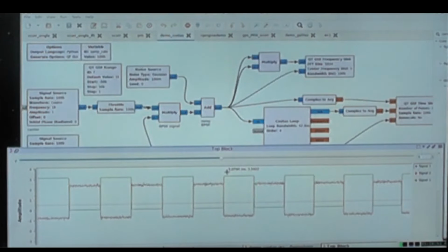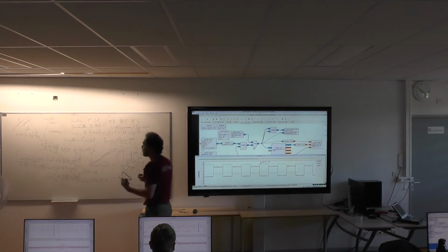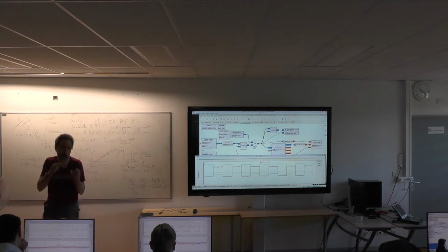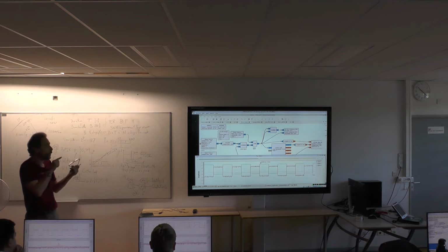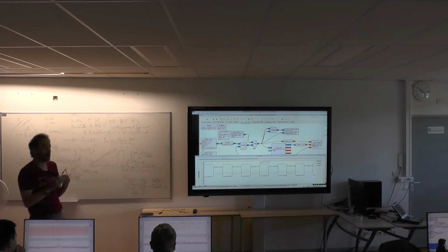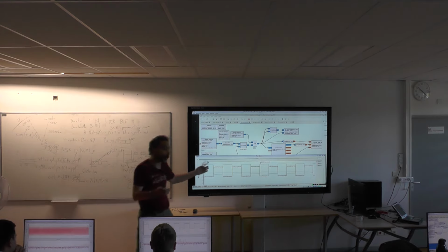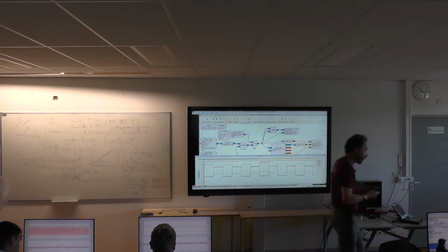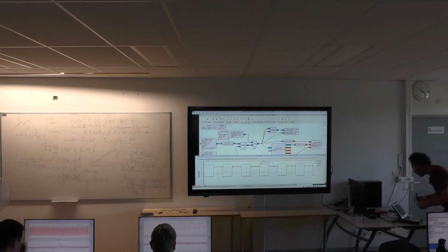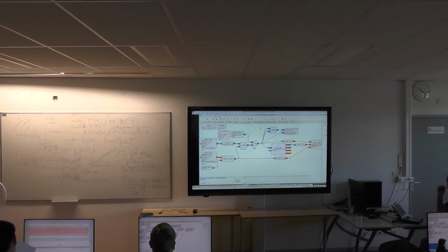Okay? So now we went together through all the steps needed for decoding GPS. You understand that we have a pseudo-random sequence. You understand how to generate a pseudo-random sequence. You understand that by correlating, we can extract the signal and improve the signal-to-noise ratio by the pulse compression rate. And you understand that we need to cancel the Doppler shift if we want to be able to detect the phase. So, with all this knowledge, can we actually process some real data?